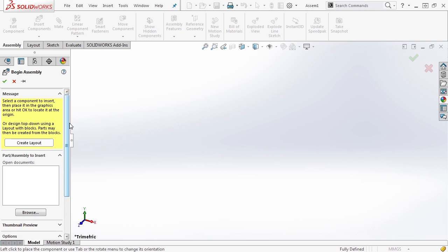Very handy, because you no longer have to suffer the performance strain of having these complicated parts located in your assembly. But with that said, it's very important that you understand that you're referencing the location of a part. That means if you move the part in your Windows Explorer, on your desktop, wherever it is, you're going to need to reconnect those references.